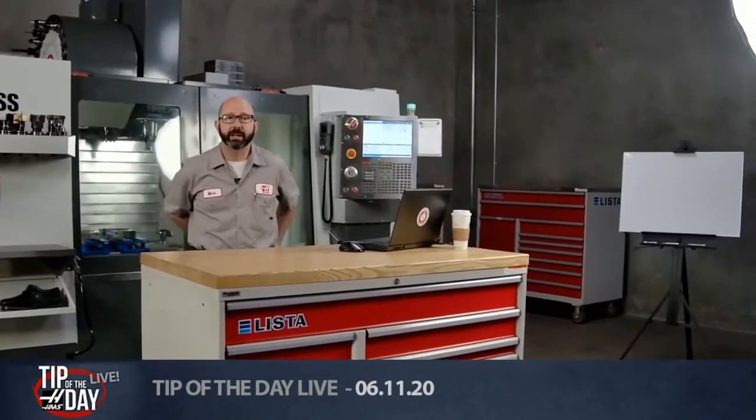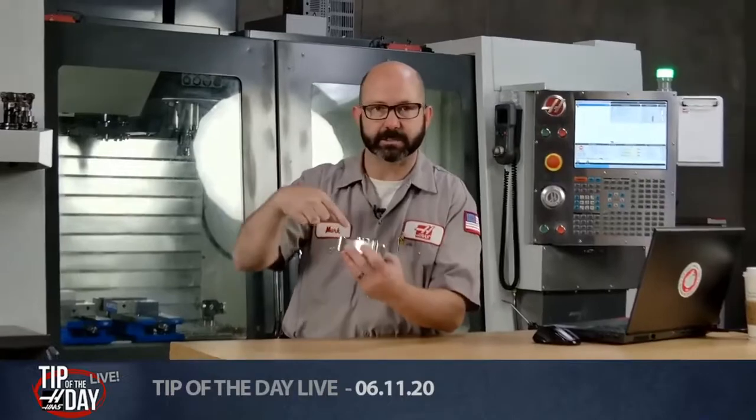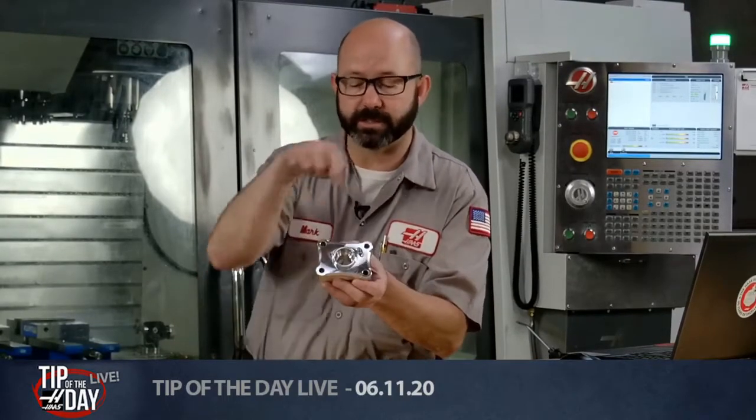Now, if you're buying a machine, just because it has a rotary doesn't mean that it's simultaneous 5-axis. You might not be able to do a simultaneous cut in all 5 axes at the same time. Some machines are only 3+2, which means it just rotates, you do your thing, rotate, you do your thing, which is good. But on almost every HAAS rotary out there, you can do simultaneous 5-axis programming. That's why people love the HAAS rotaries. You bolt them on the table, you can do simultaneous 5-axis work. In fact, I think the only rotaries that we make that only index are on some of the bigger machines. We have indexers, like a 5-degree indexer on an EC1600. But on almost every small rotary product that we've got, you can program that axis simultaneous combined with every other motion, and you're going to be able to do whatever you want. Even on our little guys, the little TRT-70, full simultaneous.